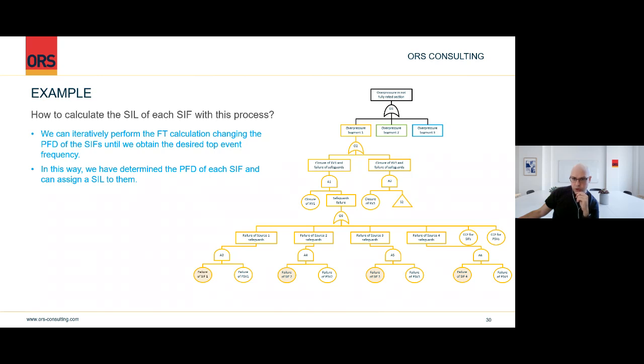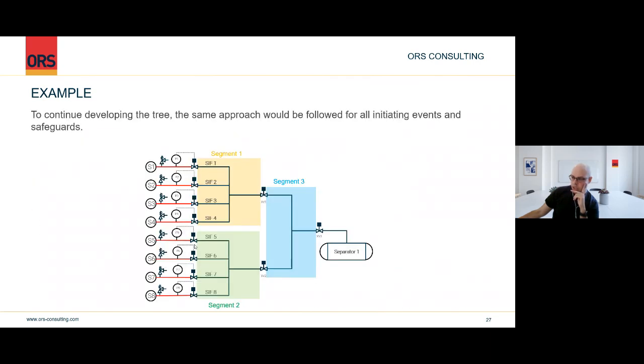So Salman also asks how the overpressure in SIF 5 to 8 can have an effect on SIF 1. It seems like a redundancy system or operating safe loop function. No, the cause is, for example, if you close XV3, you need SIF 1 and 5 and 8. You need all of them to work at the same time.